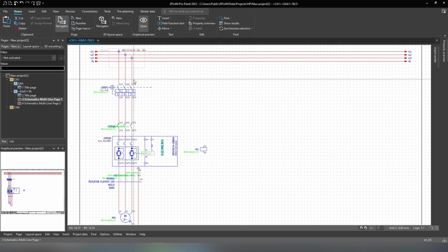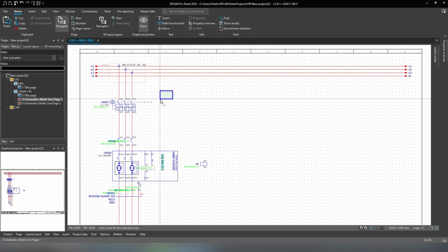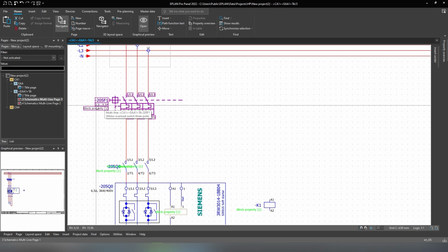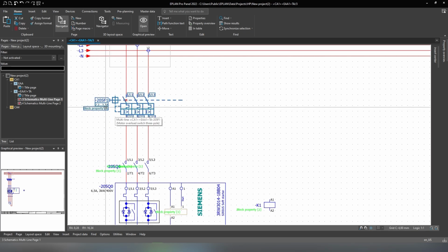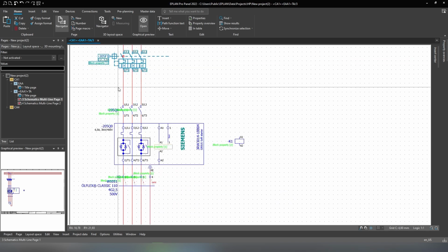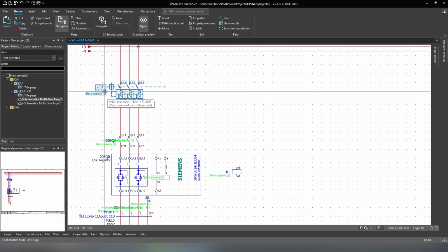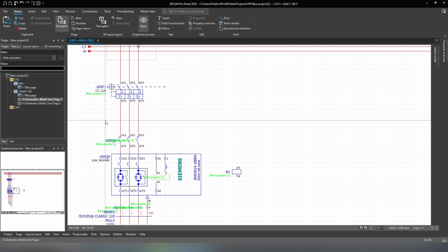And what happens with the macros to schematics page is that it prompts you and says, hey, do you want this one to be 2.2 amps to 3.2 amps? Do you want the next one to also be 2.2 to 3.2 amps, and so forth? So you can just say that at page 50, the 50th motor, I want it to be 2.2 to 3.2 amps, and the 60th motor, I want it to be 4 amps to 10 amps, for example. You can just start filling in all that information that's required.